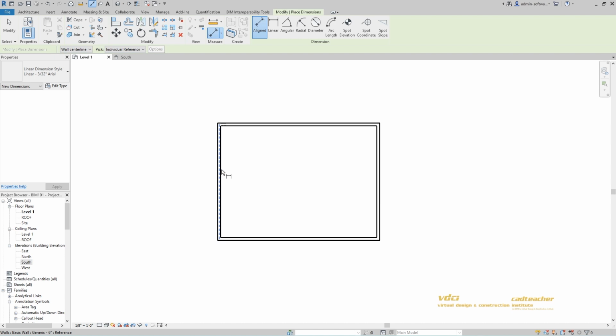So I don't mess with that. What I do is I just use what's called the tab key, which is probably going to be one of your favorite keys on the keyboard, except for escape, because that's everybody's favorite. You hit that one a ton of times here. So with tab, if I hover over the wall, I can hit the tab key and it'll change my selection options.